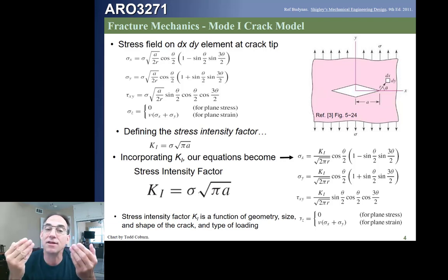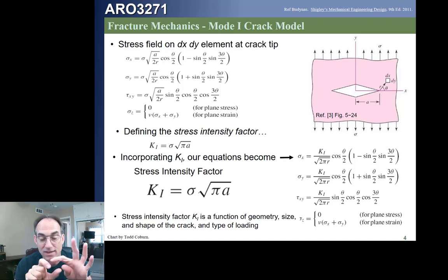So this is another thing you're going to have to be alert for when you're doing damage tolerance. When we talk about what's the crack size, right? If we spot a crack, we're talking about what the actual length of the crack is. But if we say what is the crack length, A, it's a function of what type of crack we have. And often that A is the whole crack length, and often it is actually only half of the crack length. And that depends on how that crack is defined and how it meets our parameters.